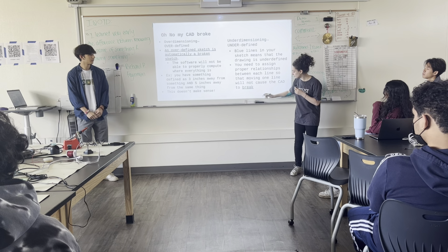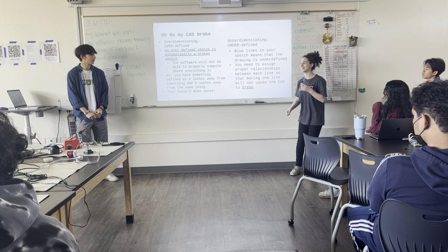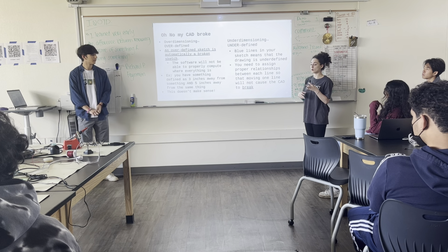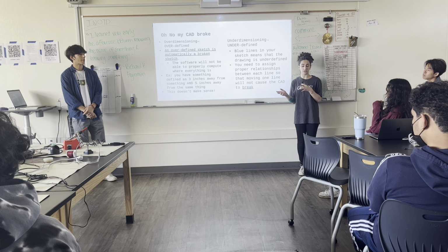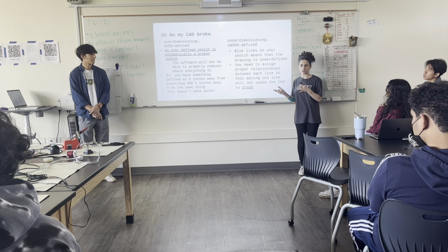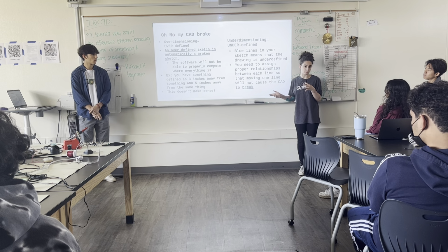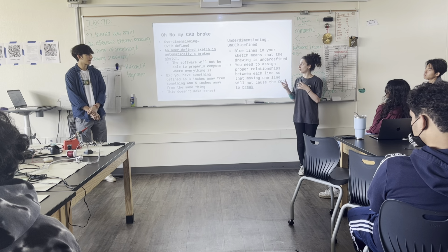All right, so overdimensioning and underdimensioning are both bad. Basically, you don't want something to be overdefined. Let's say you have too many lengths assigned to your part, the computer will not be able to actually tell you what's what, and the CAD will essentially break. It's a very similar thing for underdefined.